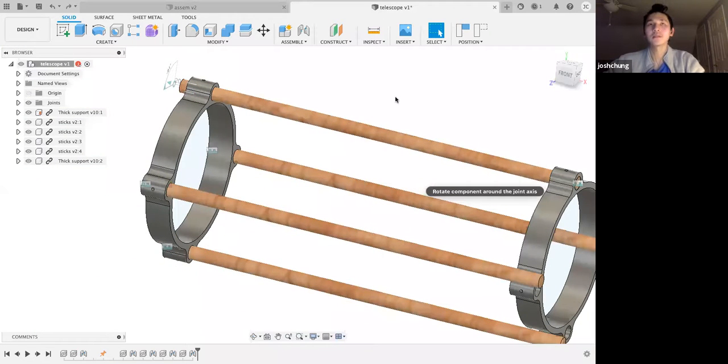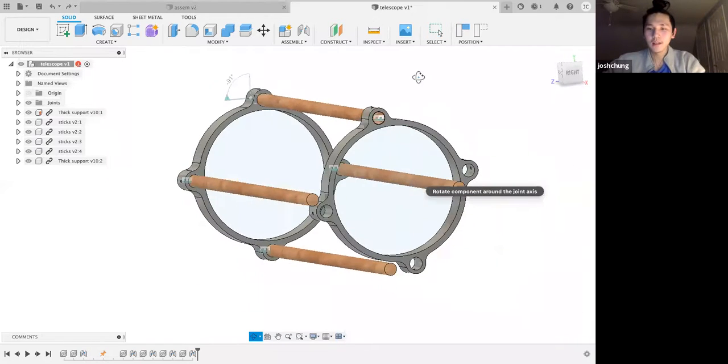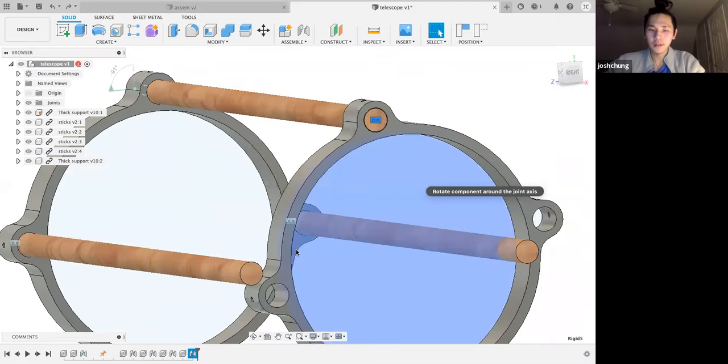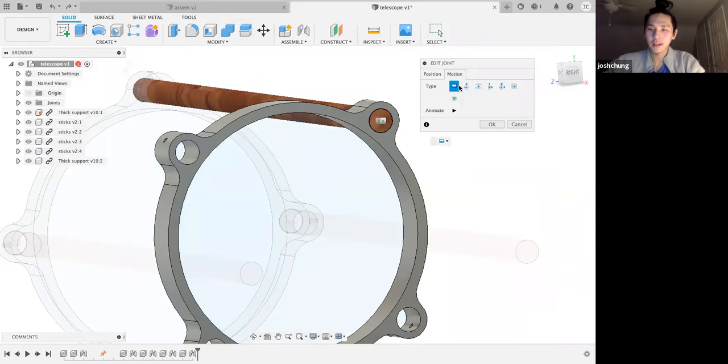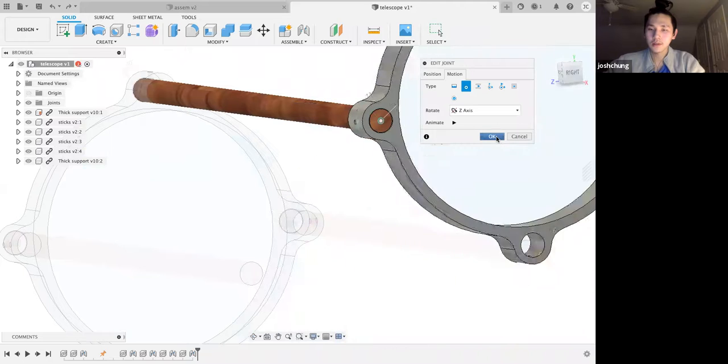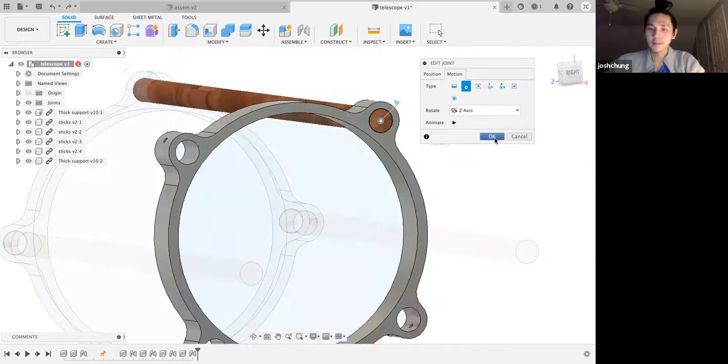You don't want to define your constraints from other constraints that you might change later. So what you would do is you would modify the constraint so that it is a revolute, so you can independently change it.